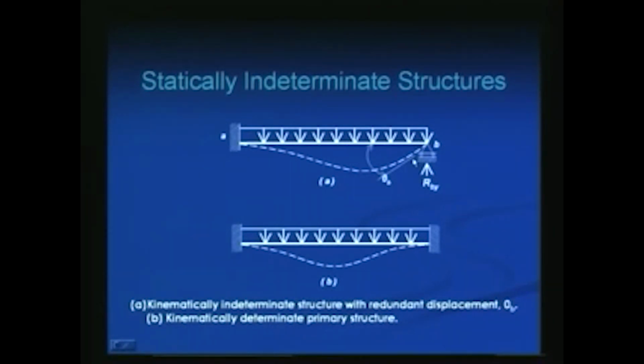Now in addition to that, I'm going to say that this is actually rigid. This is implicit. I don't even have to state it. Typically for a beam, unless you explicitly allow axial deformation, you assume it to be axially rigid. So if it's axially rigid, constraint 1. How many degrees of freedom? 1. Which is that? This rotation. So kinematic indeterminacy 1.